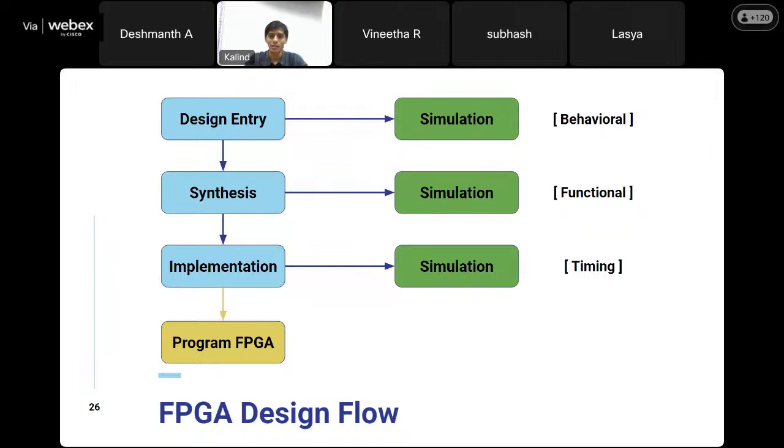After the synthesis, you again do the simulation to verify, with more constraints of the specification, that the functionality of your logic circuit is as expected or is meeting what the specification is asking you to do, right? Now you add one more timing constraint after the synthesis is done, at the implementation.